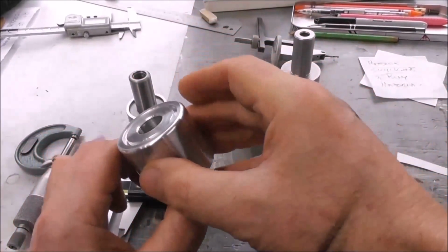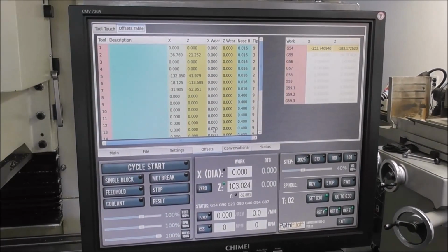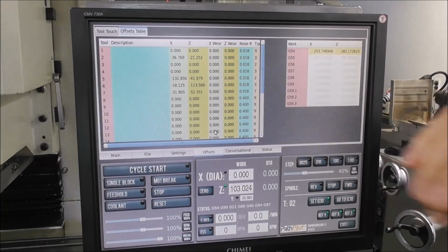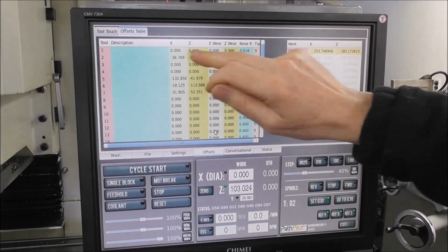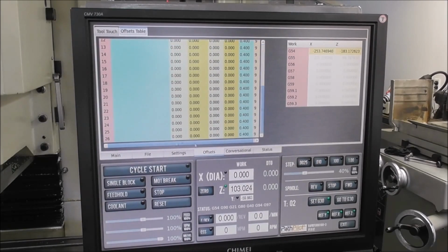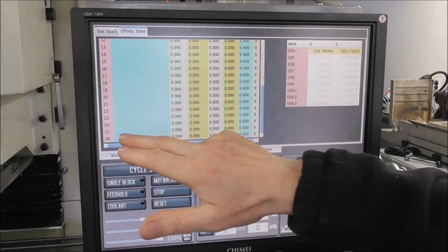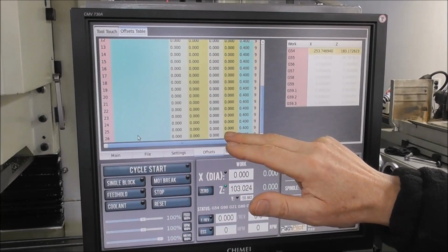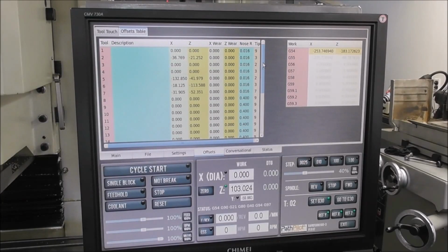Well, that's come out really well. Pleased with that. Okay, so with this video, which is about work and tool offsets for Rapidturn, I mainly wanted to go into understanding offsets better, tool offsets better, and I used the example of tool 1 to set the work offset, but it doesn't have to be tool 1. It could be tool 27. And tool 27 would be quite a good choice in some ways because it's not available here on the work offsets table, and so it's not possible to accidentally use an existing tool or with values that you don't want in there. But I've used tool 1 because of Daniel Rogi's excellent video.